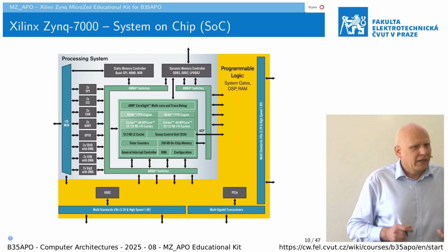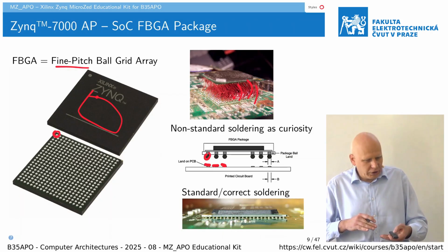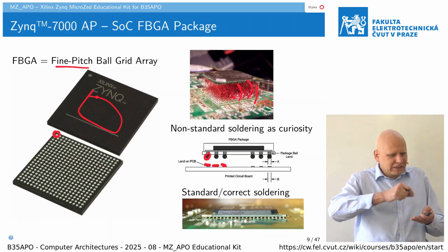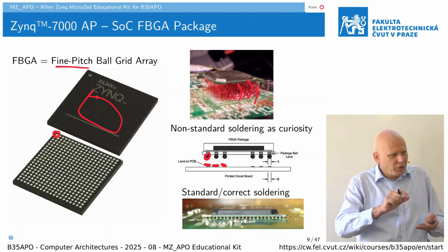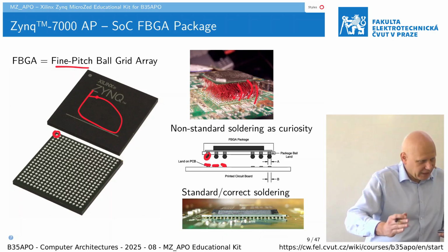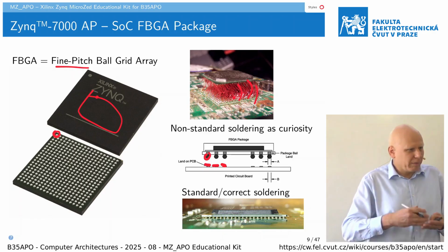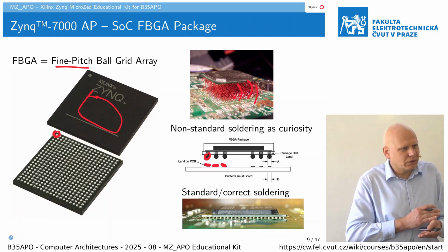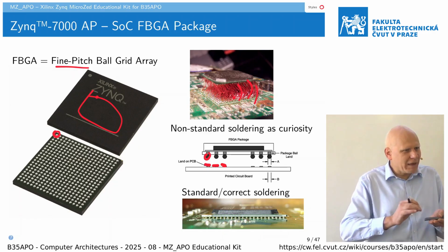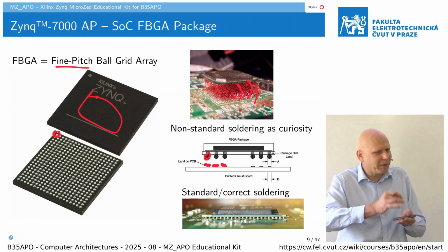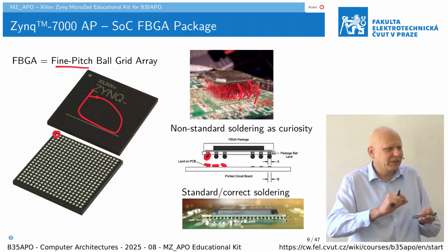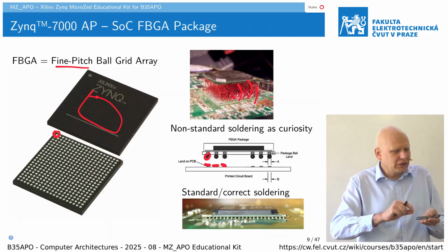Okay, if you want to solder it on the board, then there is one technology step where a dispenser puts the small drops of the paste. Yes, and if you strip it away and want to reball it, then basically you need to clean the pads and then put there a small amount, or ideally dispense with a dispenser, ideally robotic, which dispenses an exact amount on each of those pads.